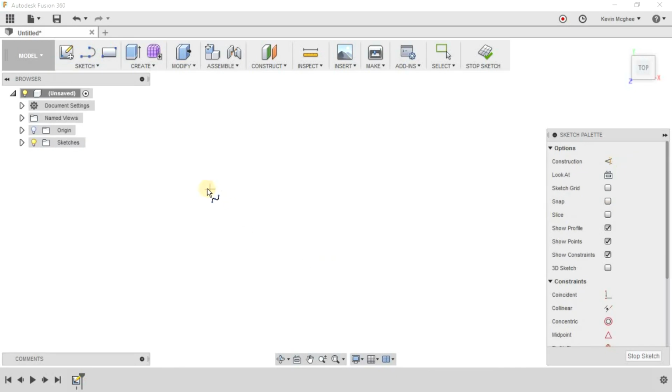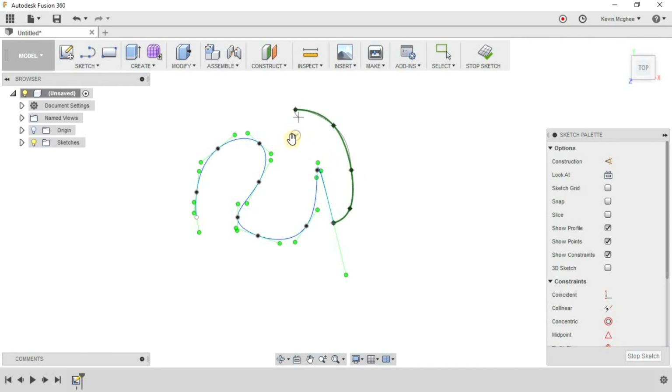Spline is going to be your most useful tool for using canvases for modeling, because on curved pieces you just start placing points and you can curve things around. When you get to a sharp corner, it doesn't look very good. It looks really bad, and it changes what you've done before. So I generally will just close it and then start again from that point if I want a sharp corner,